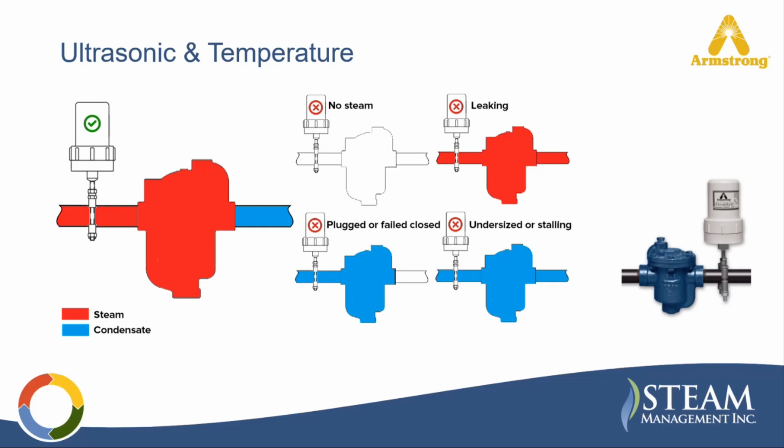But if our temperature set point is achieved, then the monitor begins listening to the trap using ultrasonic technology. Every steam trap sounds a little different depending on the trap type and operating conditions. However, one general rule tends to remain true across the technologies. A healthy trap is typically hot and relatively quiet.